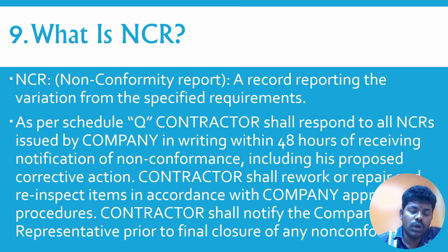In case you go to site and check the joint and the welding, and there is a difference between the WPS and the current during welding, they change the current, the voltage, the electrode, or the material, so you raise the NCR.